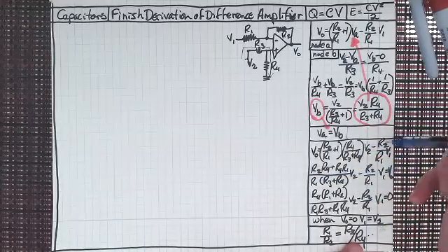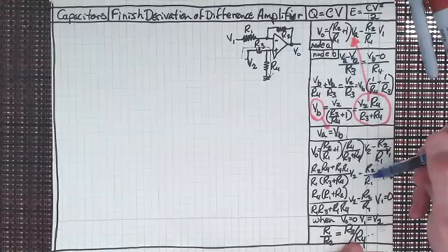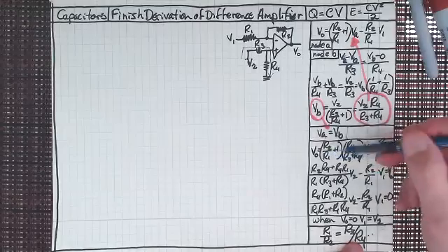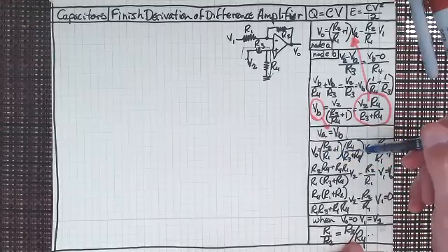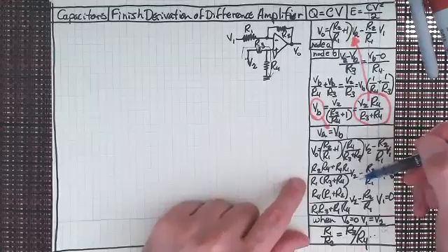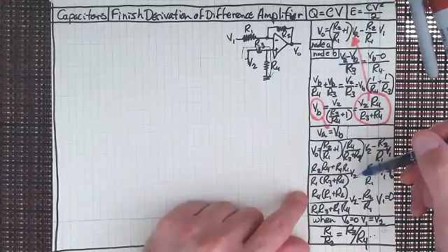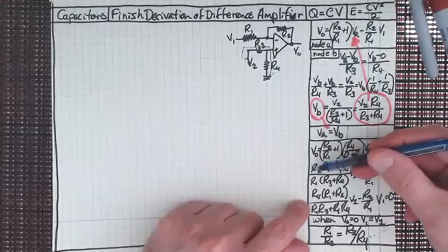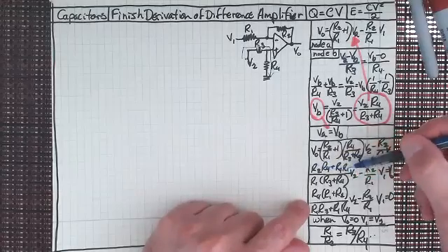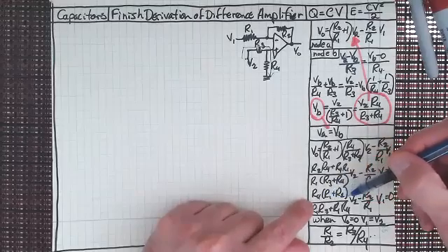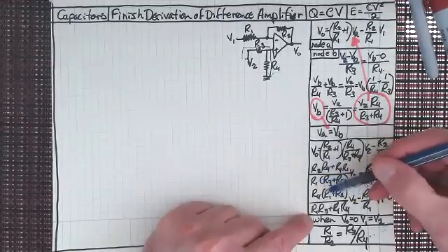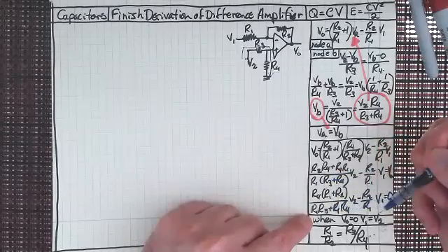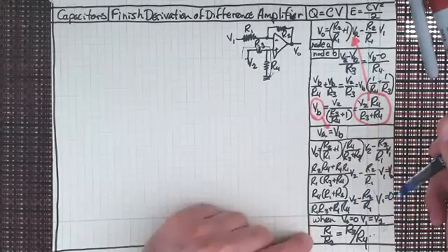I think everybody can see what I've done here. I'm still keeping the R2 minus R2 over R1 V1. That's always the same, but what I'm doing is I'm simplifying this expression that I've got over here into V2. And then I take this a step further because I've got R4 as a common multiplicand in that, so I could take that out. And then on the bottom, I've got R1 times R3 plus R1 times R4, right? V2 minus R2 over R1.